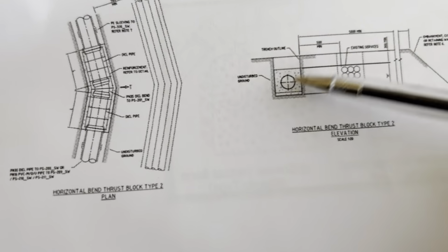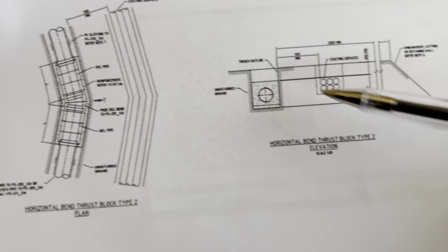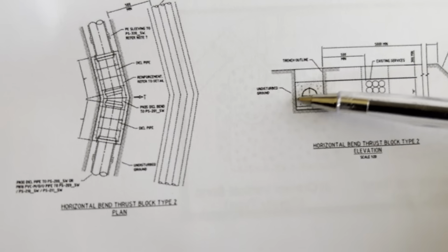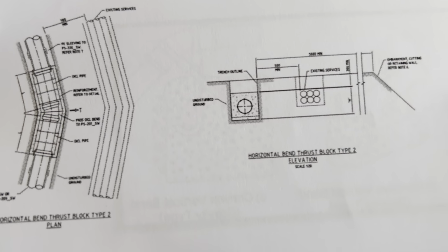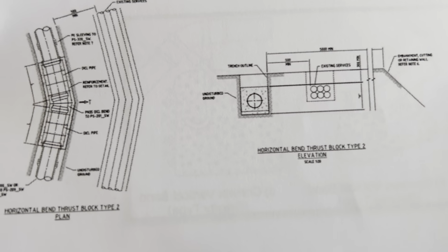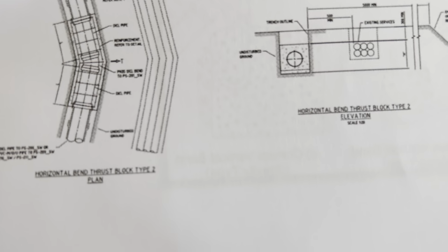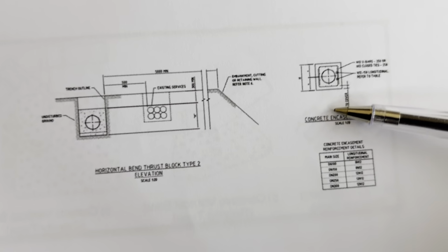And also take the load itself. In the general case here, because it is something like a bending section, we need to have reinforcement all around the pipe because it is a bending system. And it's like an encasement. It should be heavy, and also it should be strong for bending to take the loads.